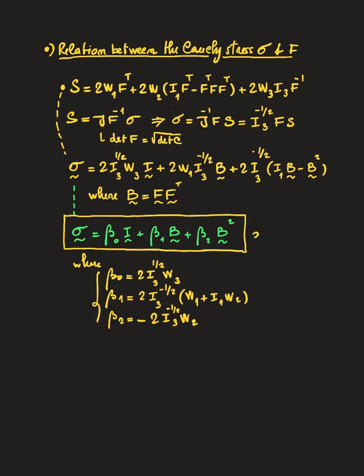So you see, sigma is in fact a function, if you want, of B. Yeah, this is rather interesting because if you remember, the Cauchy-Green tensor B is a tensor that lives only on the current configuration. It's what is called the Eulerian tensor. So this is an interesting way to express the dependence of the state of stress in the current configuration, because there are many situations in which you want to work completely in the current configuration. For example, I can anticipate that in fluids there is no reference configuration, and for this reason there is only the configuration that you are observing.